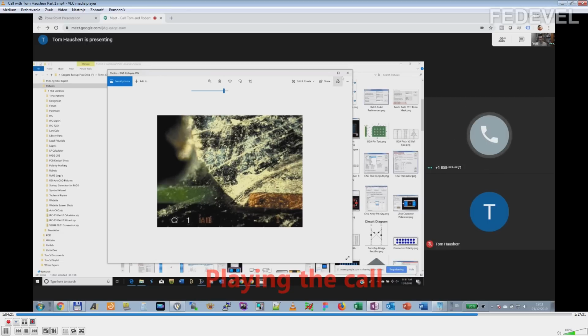Solder mask define would mean that you take the solder mask and you bring it over the pad a little bit, by 0.05 millimeters, okay? Just bring the solder mask over the pad, and then when the ball melts, it's going to create a good solder joint on the pad. And when you go to the drop test, the solder mask will keep the pad held down to the pre-preg.